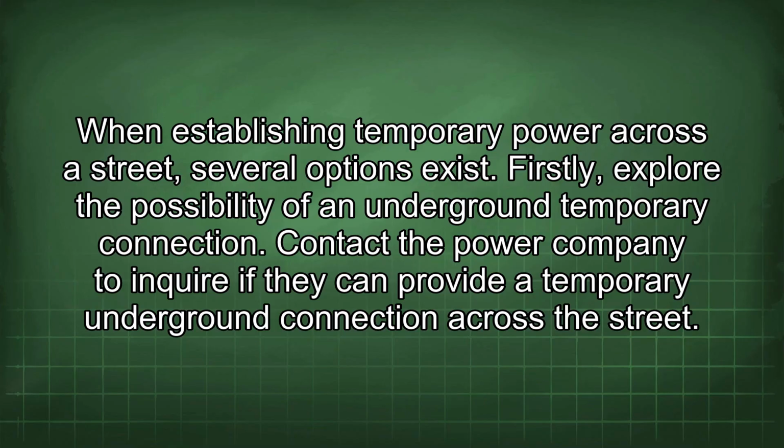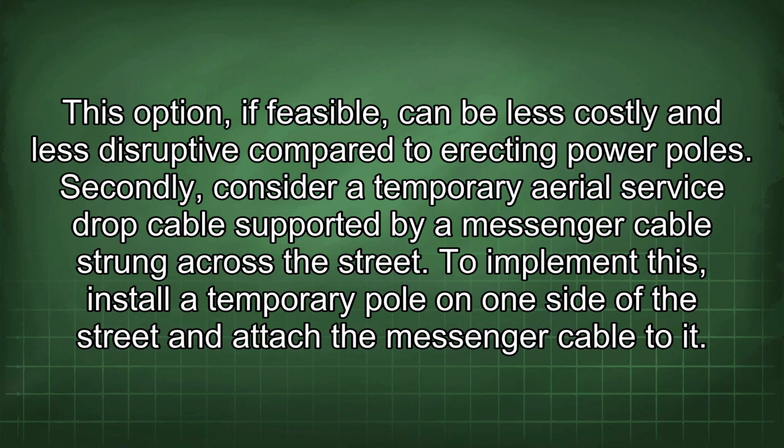When establishing temporary power across a street, several options exist. Firstly, explore the possibility of an underground temporary connection. Contact the power company to inquire if they can provide a temporary underground connection across the street. This option, if feasible, can be less costly and less disruptive compared to erecting power poles.